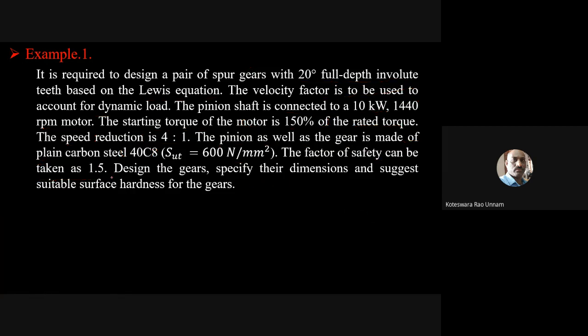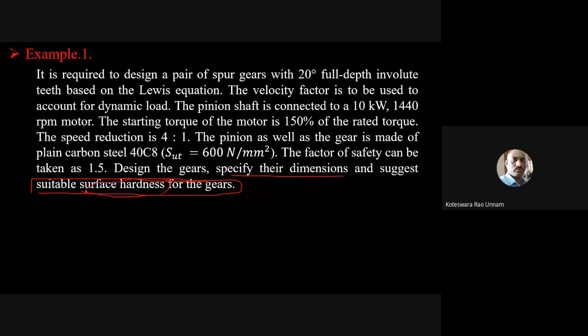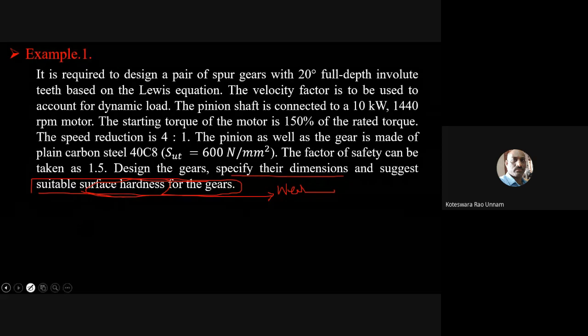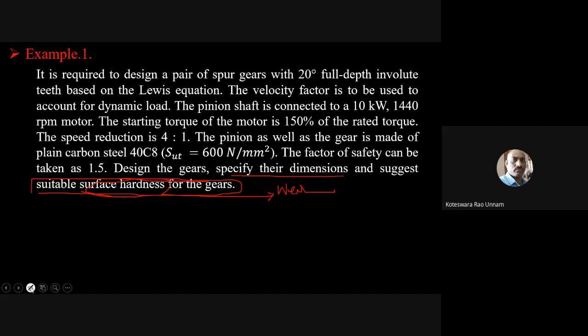Okay, then what you are asked is to design the gears, specify their dimensions, and suggest a suitable surface hardness of the gears also. Surface hardness comes from the wear point of view. So based on the wear strength equation, you need to calculate the surface hardness required. We'll see all these things one by one. Now we'll see step by step the solution for this problem.